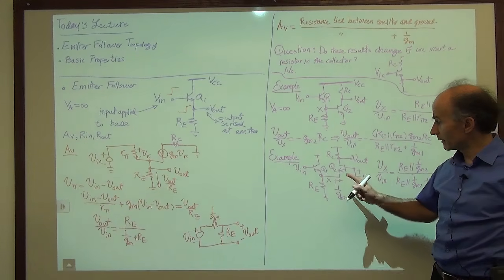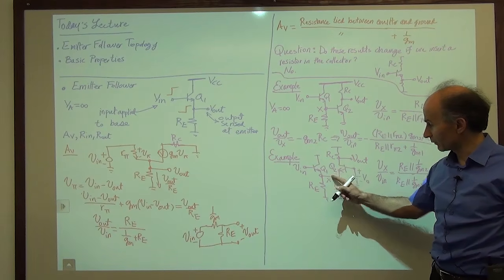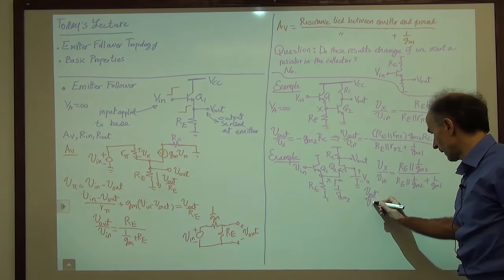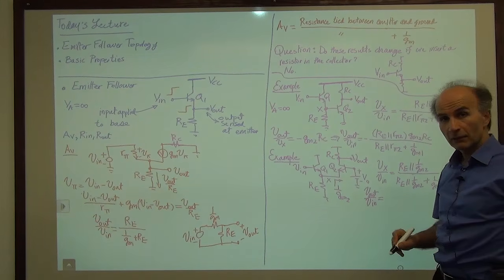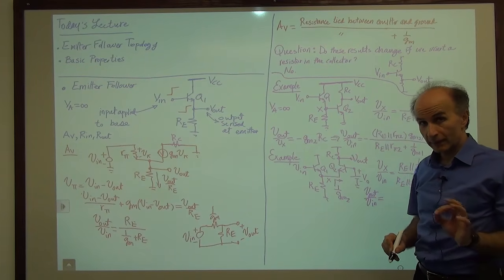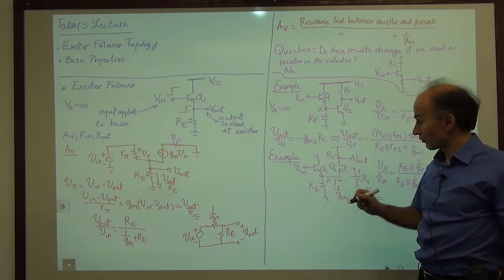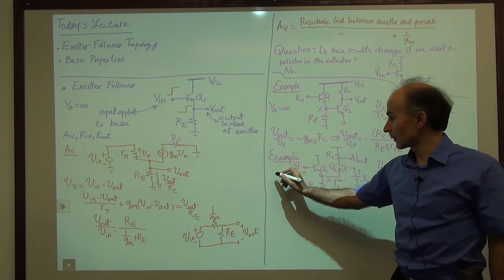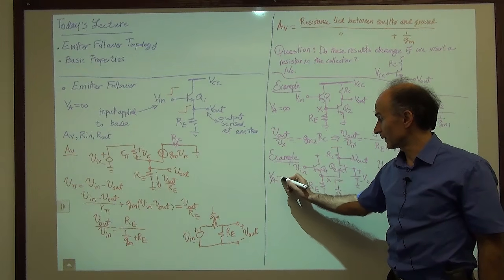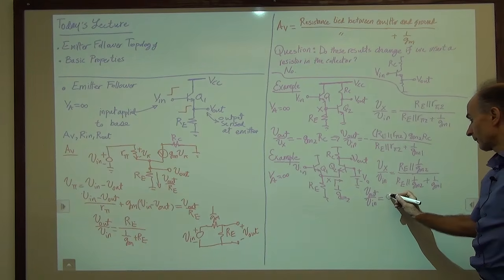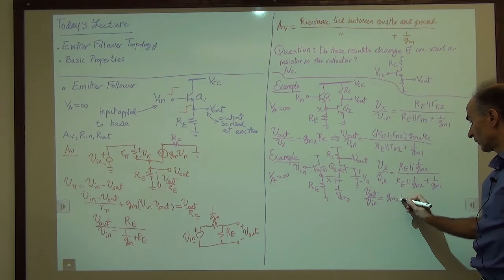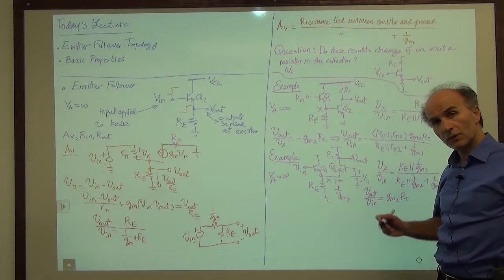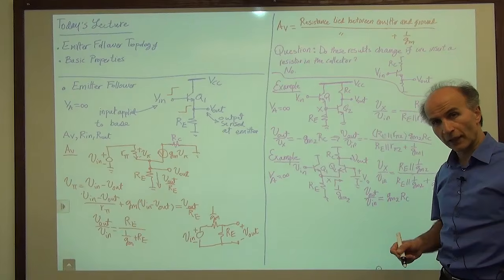And what we need now is the voltage gain from X to V out, so V out over Vx. And we know how much that is. V out over Vx, that's the voltage gain of a simple common base stage. For a common base stage, the gain is positive Gm times the resistance tied between here and AC ground. So again, all of these, we're assuming that the early voltage is infinite. So we have Gm2 times Rc. And the total voltage gain is just a product of these two. So I'll leave that for you to write.